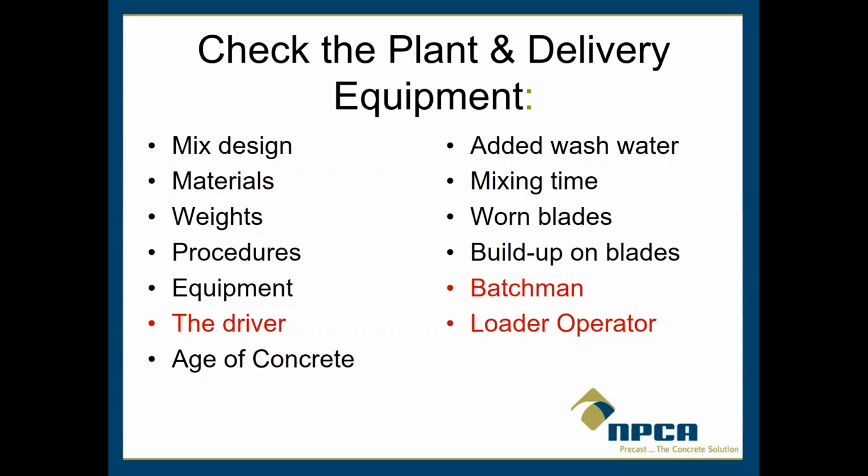If you're in a ready mix truck delivering in the yard, was wash water added, or even added in the plant? Mixing time can be a huge factor with a lot of variables, including slump life and air contents. Worn blades in the mixer or buildup on the mixer blades will oftentimes impact what happens with the air and the slump. And then the batchman and the loader operator.